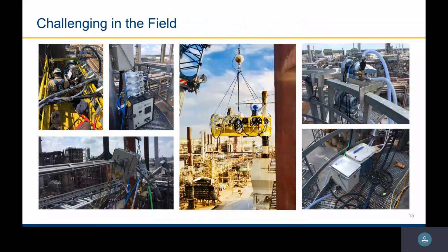Here's how it looks on our test program that we were doing in the field. We did quite a bit of it out of cranes. We didn't have sample stack platforms on some of these. This is the console and the mass flow controllers that control the flows of the filters. Here's the actual probe and hot box hanging on the monorail that's off screen to the left. And the apparatus where we pull and dry the incoming air, before that cool air goes in.